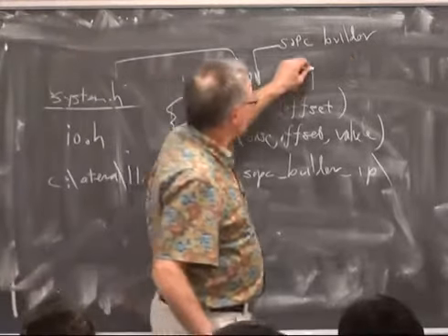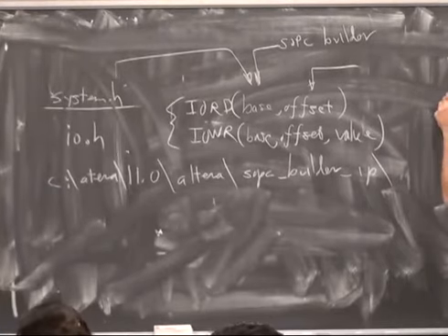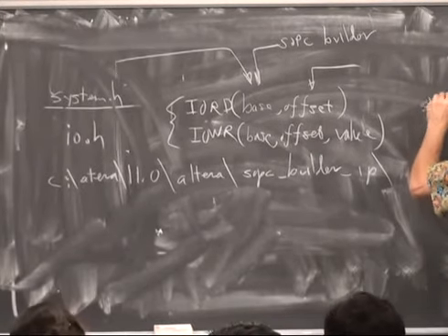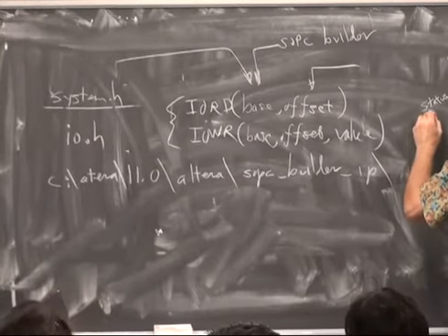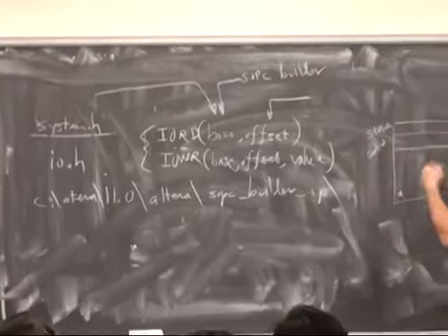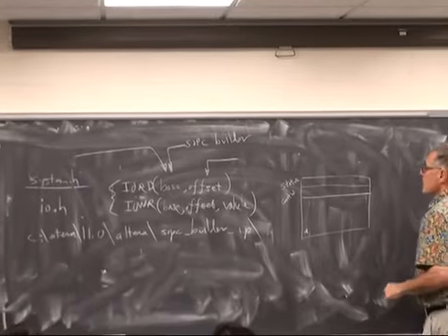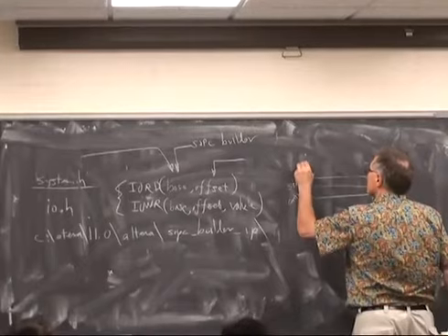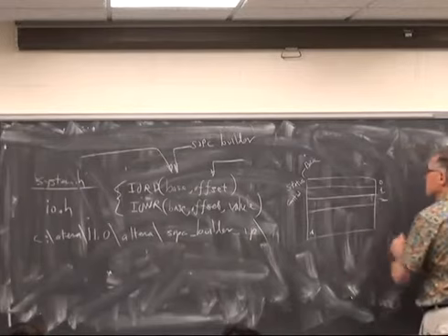The offset for a given register means the following. For instance, a timer block has a base address. The first word is the status, and the second word is control, and the third words are some period stuff. So this is offset 0 within the block. This is the base address. This would be offset 1 and offset 2 and so on.